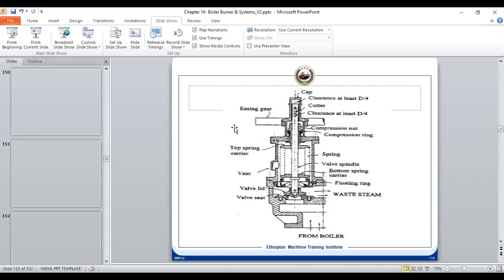Where was I? Okay, now your periodicity of your so-called dry docking is about 30 months. But in the first 30 months, we never do the ship's dry docking, we do an in-water survey. After 5 years, that is 60 months, we do a proper dry docking, in which we take the ship to a proper yard and do it.